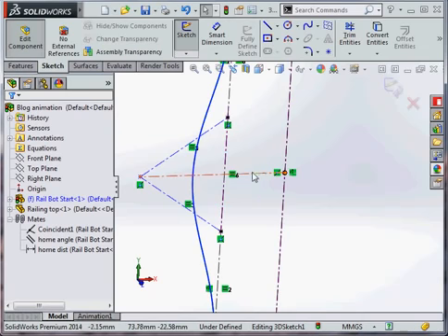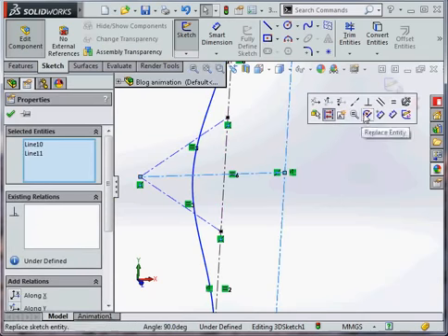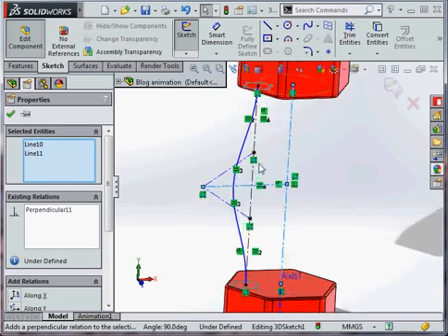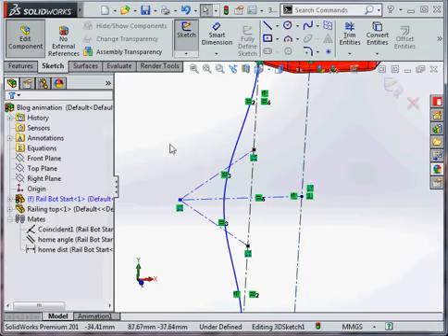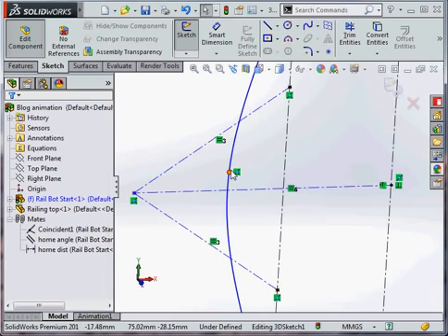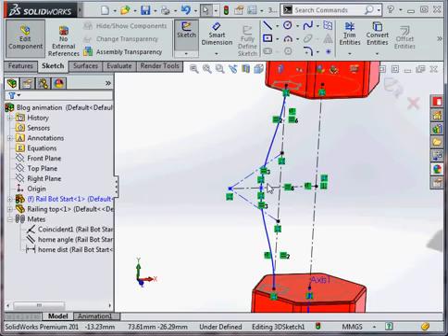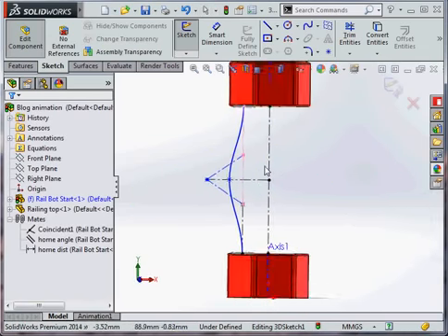For instance, we're going to add a little controlling spline here. Just remove the along X, and we'll make that perpendicular. So I'm removing the along X so this can rotate, and the angle of this item here can change with it. I'm going to add one more, which is going to put a point on this spline and connect that point to my line, just to gain control. Okay, so that's more or less my spline set up.